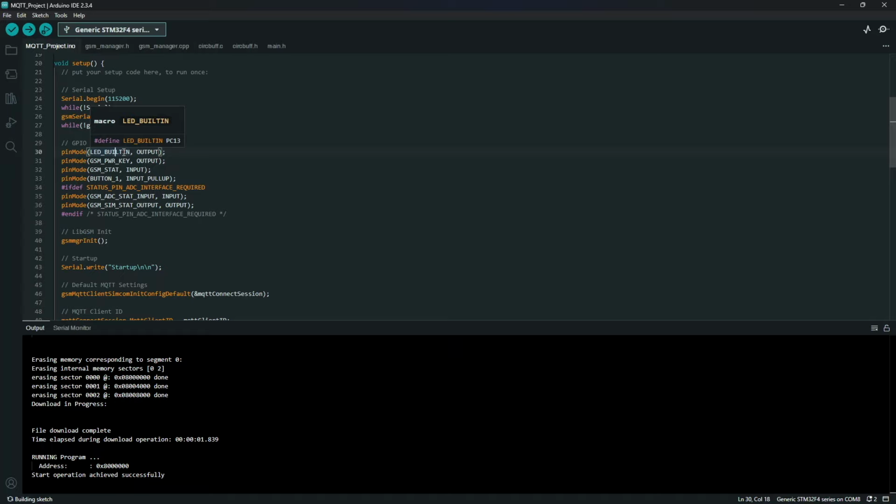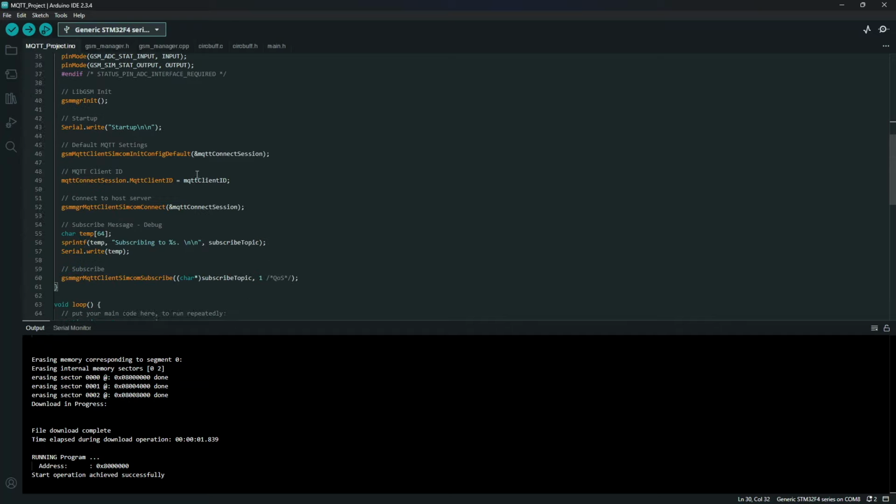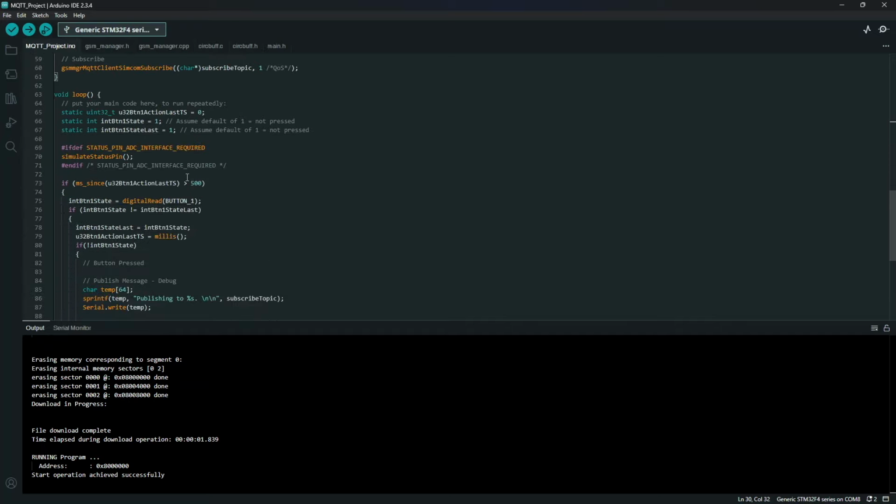So if you've interfaced your Blackpill with Arduino IDE, as I stated at the beginning of this video, that will be already defined as PC13. If you're not using the Blackpill, please just make sure that this is already defined to a built-in LED, or if you're using an external LED, that you just define a pin in your main.h that this LED is connected to. After we've done that, the next thing that you want to do is scroll down to your loop routine.